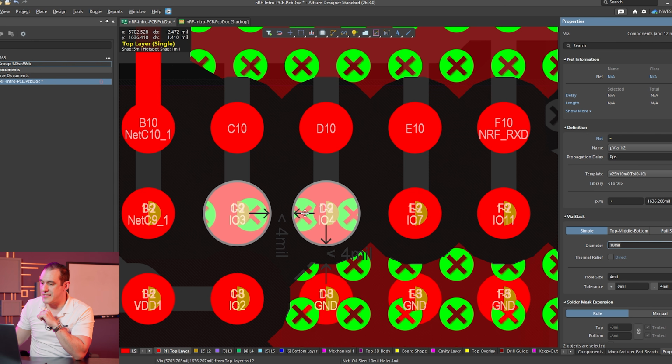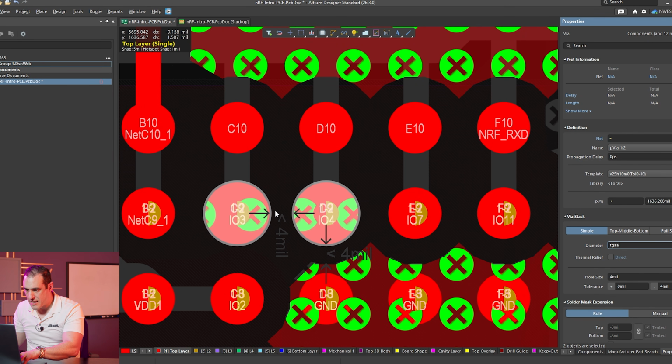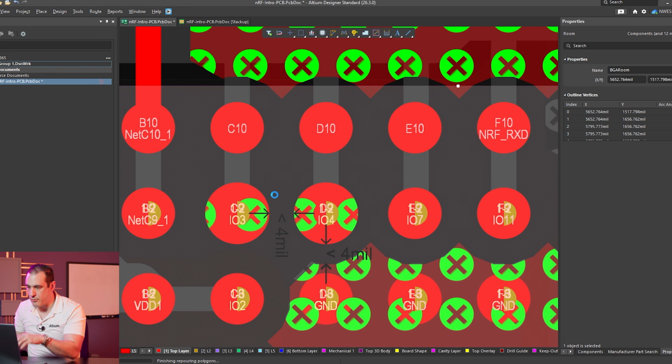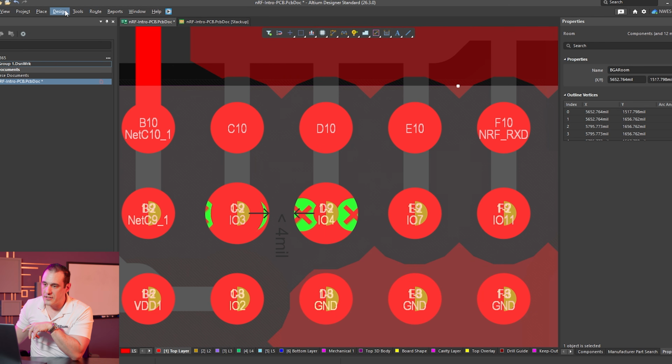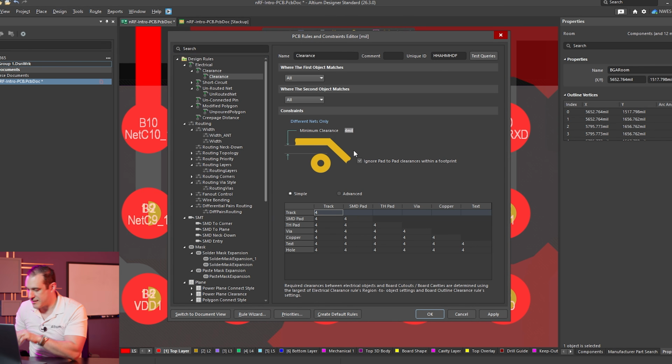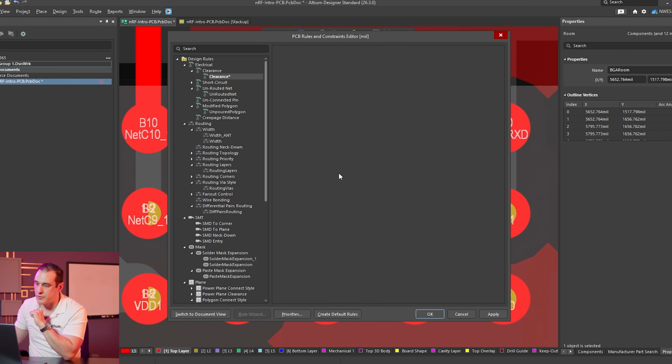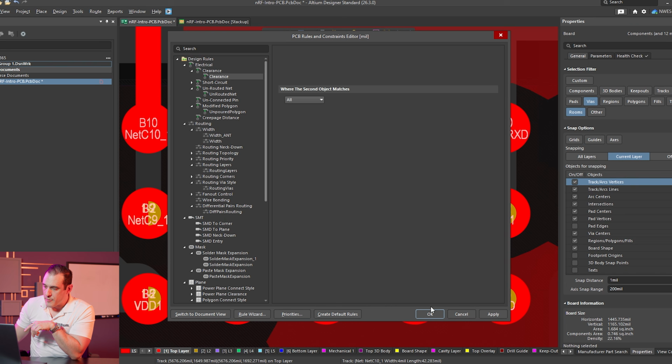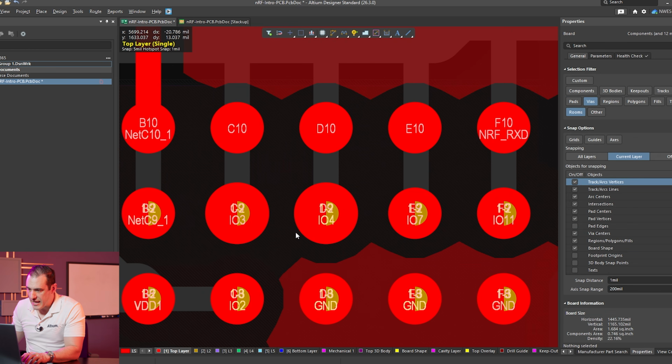So if I enter in that 10 mil pad size, you can see here that we have some clearance violations, and we're just going to want to make sure that we re-pour the polygons. And then let's go ahead and also update the rules so that we clear out that DRC, and then we're going to set the minimum clearance to 3, which was one of the values inside of their table. So after I define that clearance value at 3 mil, I'll just go ahead and hit OK. And you can see here, this is what the layout currently looks like.